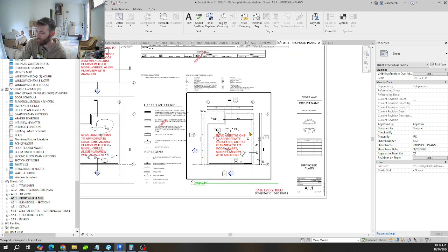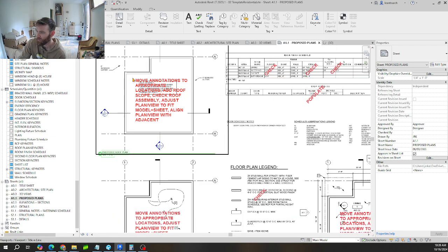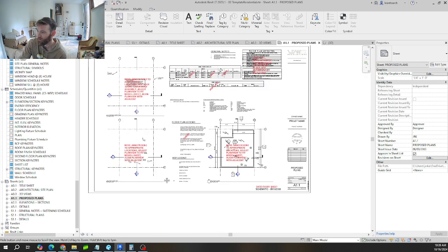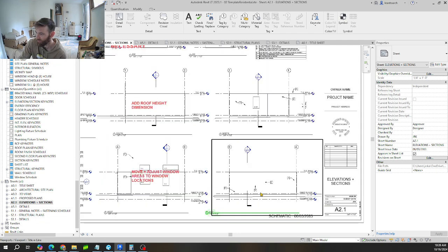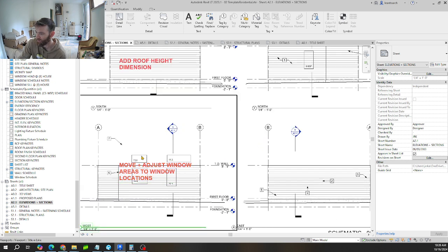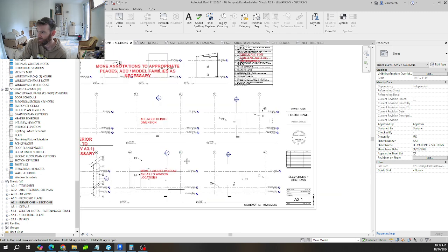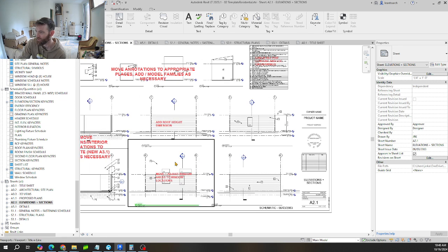Outlets typically go on your floor plan, where switches go on your reflected ceiling plan. And we have no roof on the project yet, so all we're seeing is the walls here. Jumping into elevations, you've got your exterior elevations. We have to show fenestration, or opening and window areas, and that they meet our requirements from the residential code.